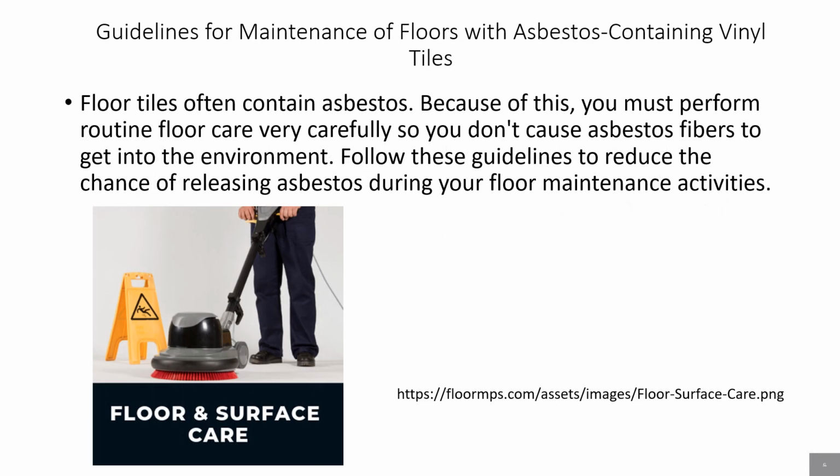Guidelines for maintaining floors with asbestos-containing vinyl tiles. Floor tiles often contain asbestos. Because of this, you must perform routine floor care very carefully so you don't cause asbestos fibers to get into the environment. Follow these guidelines to reduce the chance of releasing asbestos during your floor maintenance activities.